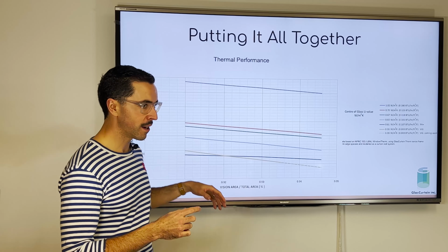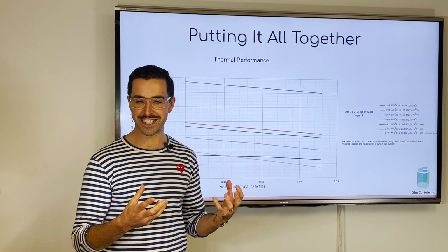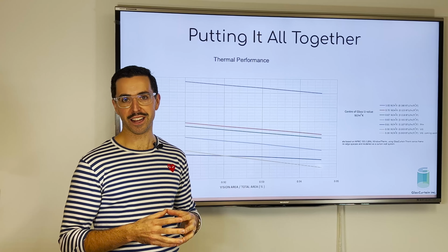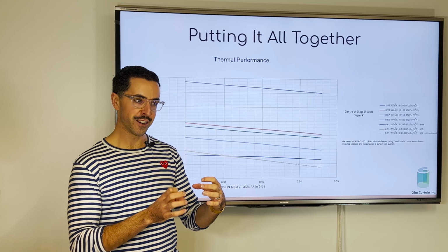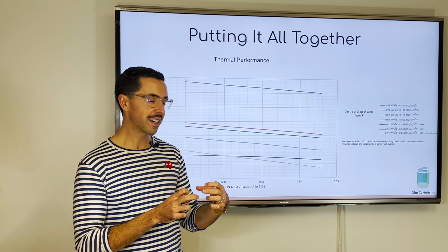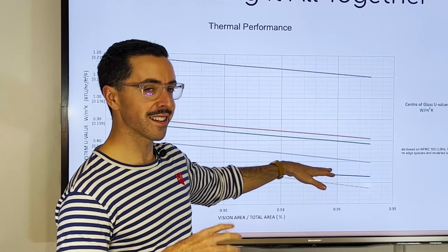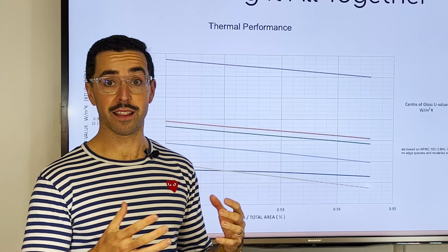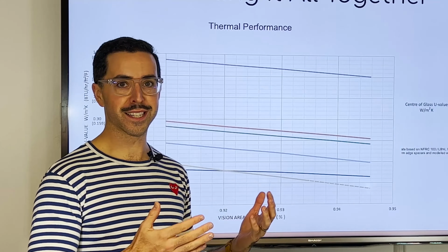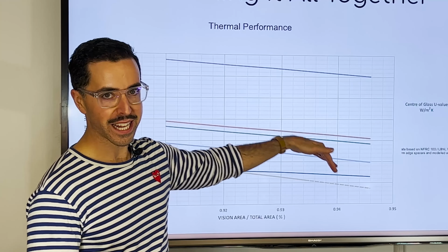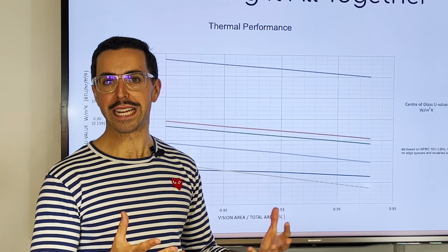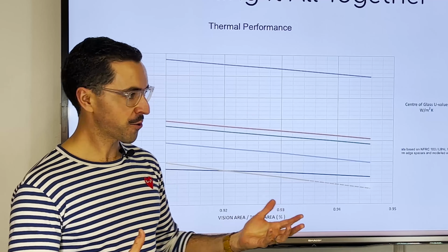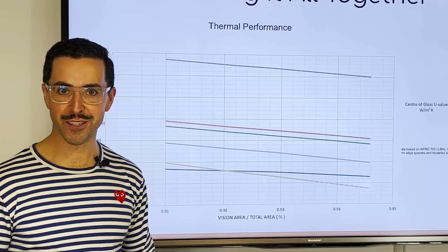Our passive house system is our new framing system with reinforced nosing area essentially, with higher thermal performance in that sort of critical section of thermal bridging. And we can actually see how flat this line is to show how insulating that frame is. The worse insulating the frame, the steeper these lines are going to be. The better insulating the frame, the flatter these lines are going to be. And that's sort of how we read a thermal chart.